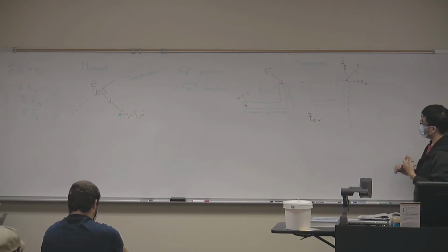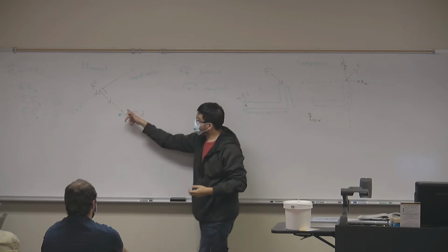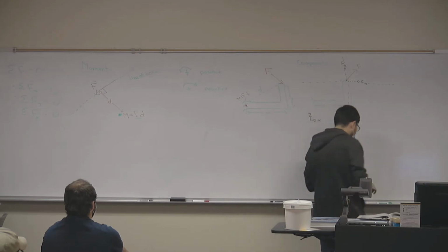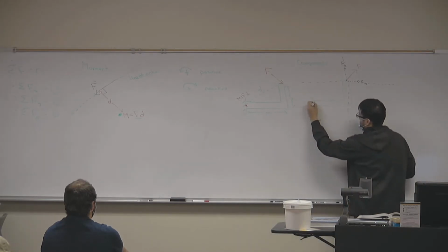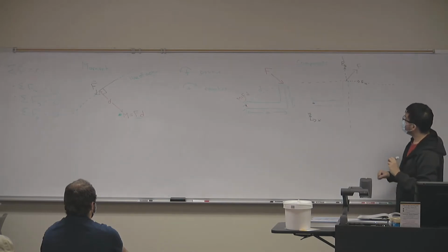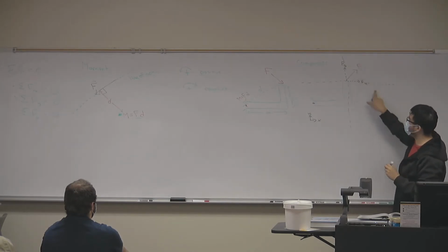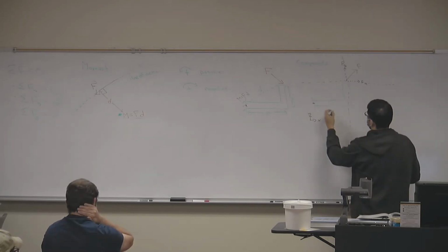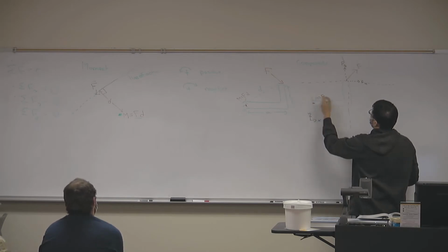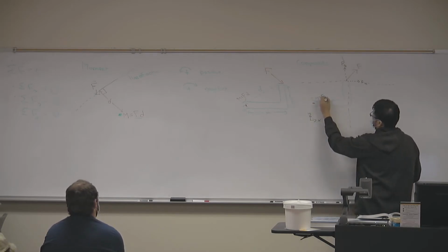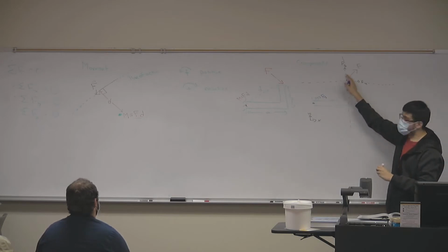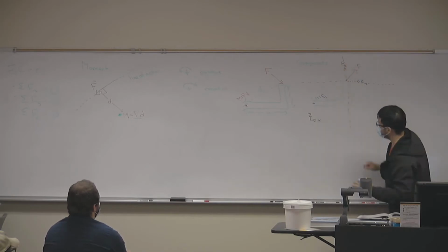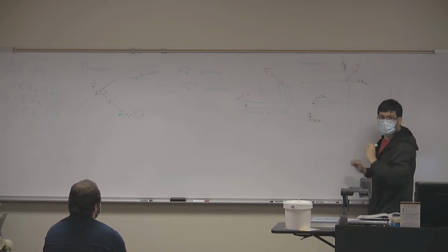Now, we mentioned that the distance d is the distance that gives you a perpendicular, a 90-degree angle between your point and the line of action. So if I want to find, once again, the moment about this blue point, and instead of using my total force F, I want to use the components of my force, then I can say that the moment is equal to, let's say, the y component of the force, F sub y, times which distance? What do I have to measure to multiply it to get? Horizontal distance. Exactly, the horizontal distance, right?